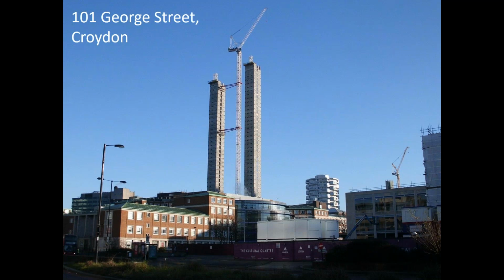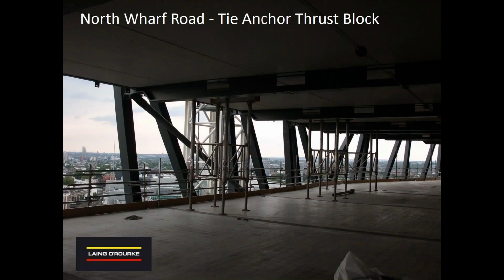The other option, as I said, is a bridging column. The other obvious option, so I haven't actually, as part of this slightly reduced size presentation, got a photo of a bridging column, but they're quite common. I mean, this obviously is a photo showing 2 concrete slabs of a building. A bridging column would be much heavier than a gas leg, which is what you can see here, typically sort of 300 square hollow steel sections.